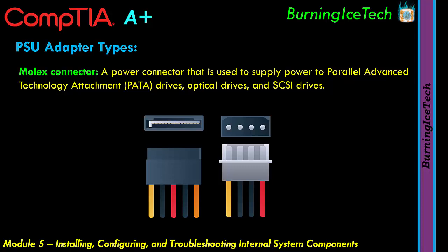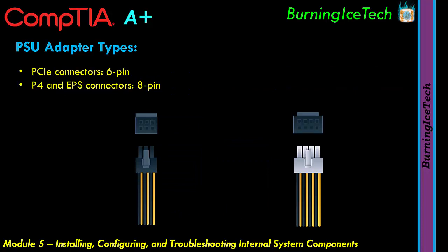They're fancy. Here are some extra power connectors that you may or may not see. Now these ones are normally for extra things like graphics cards and stuff. So if you go buy yourself a normal power supply, the cheapest kind you can find, they will probably not have these pins on them. You're going to find one that's got like 4 extra pins just dangling around. That's normally one that connects directly to your motherboard, besides the other 24 that we were talking about. That 4 one, we call it the P4, connects normally directly next to your CPU. So it's between the CPU and the back of the case in most cases, but it could generally be anywhere around the CPU vicinity.